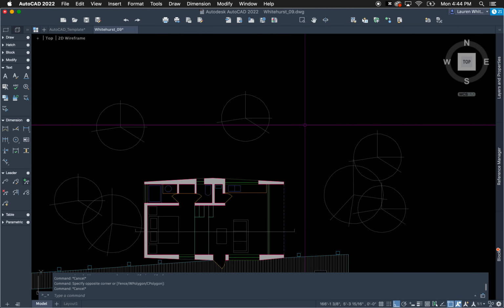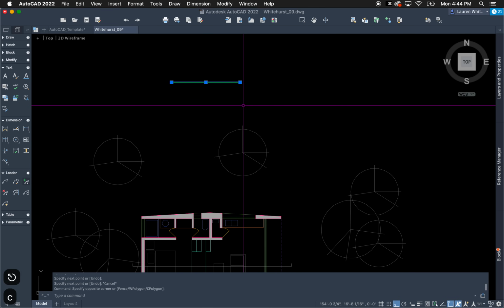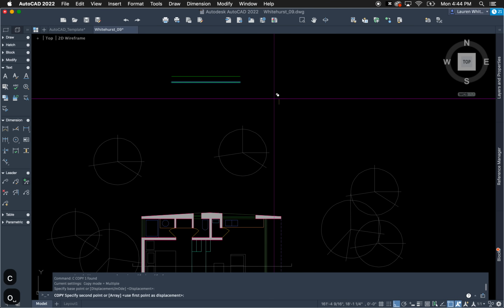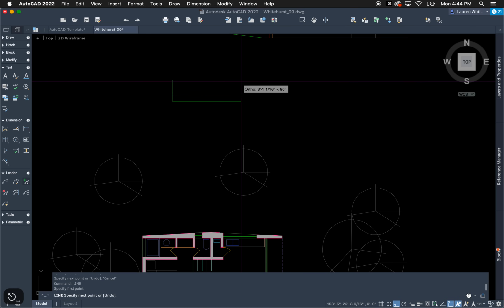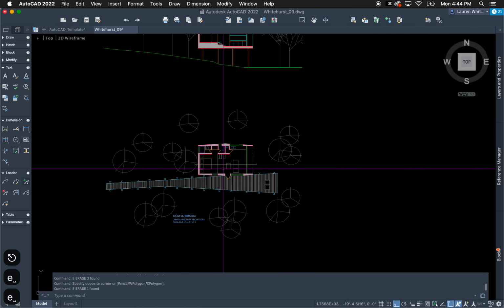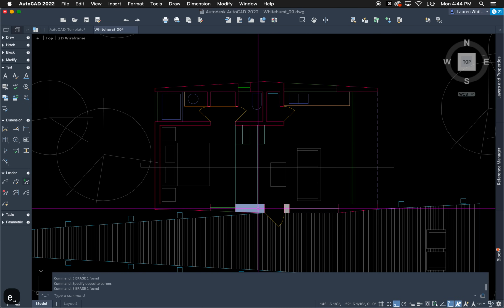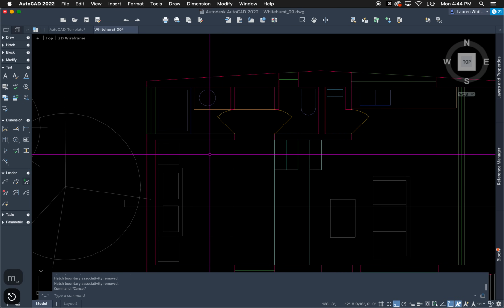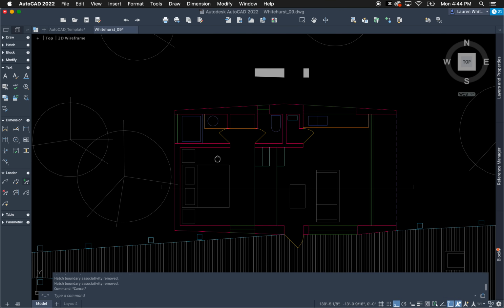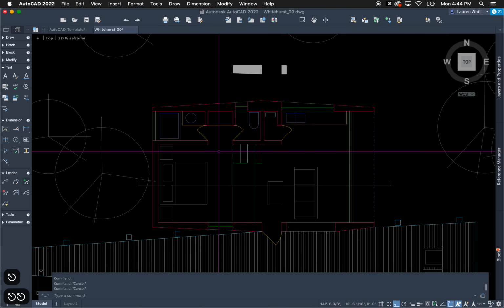Once you have the walls drawn, one thing I haven't gone over yet is what's called hatching, which is how you get poche. So if you've drawn all your walls and you want to poche them, pink is the layer that is the walls. One way to do this is to isolate layers. And hatch, it's easier that way.